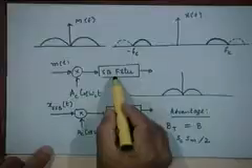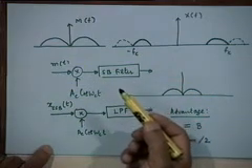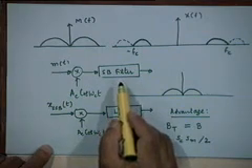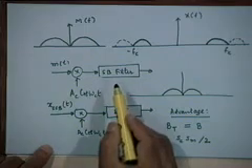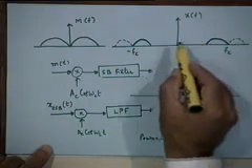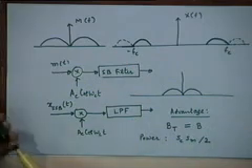Let's discuss briefly the issue of practical realization of the SSB waveform. The additional thing that you require on top of what you do in DSB-SC is this sideband filter. Now this is a non-trivial operation that you want to do. This is what you need to understand. You require a sideband filter with almost ideal characteristics. Suppose you decide to retain the lower sideband. So what kind of transfer function should the filter have?